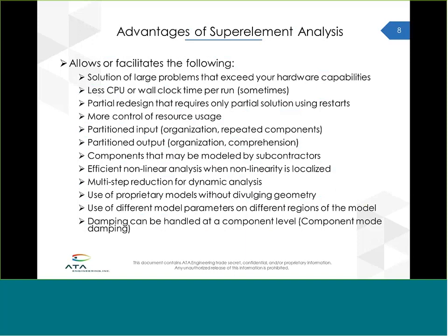Some of the advantages, this is a pretty long list. I'd certainly invite you to read along. I'll hit the high points. My impression of why superelements were invented was that a very long time ago they didn't have the computational resources we have today, and they wanted to solve models that were too large. So they came up with this process where you can essentially take your model and never have to solve the entire model at one time.